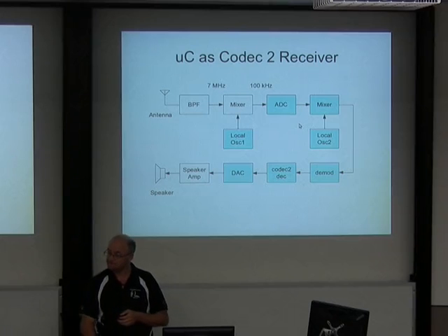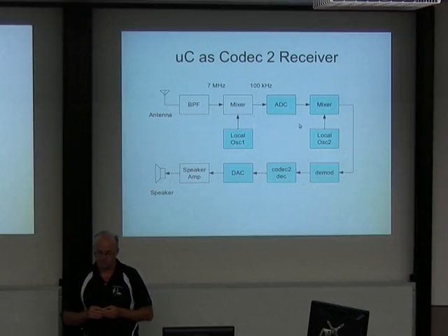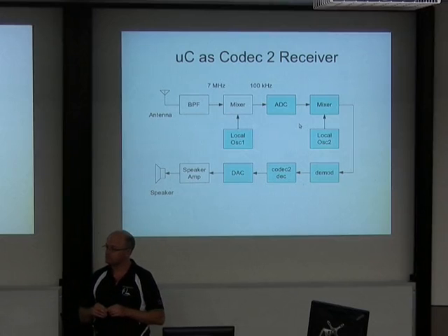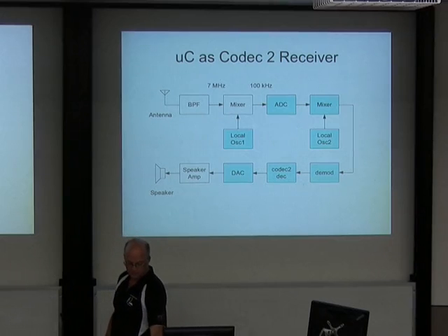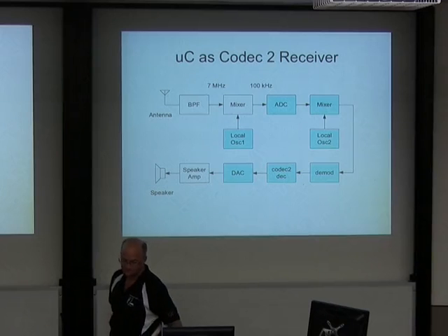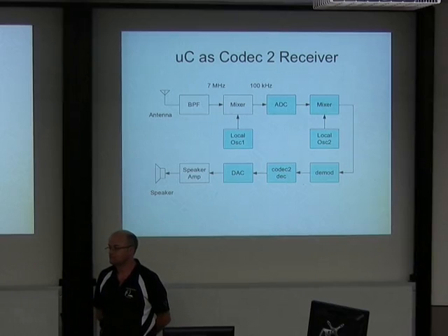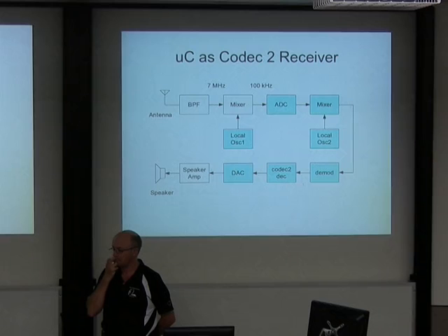So traditionally, what you've essentially got there is a superhet receiver. Yes. And traditionally, the point of a superhet receiver was to prevent noise getting in, so you mix it down to an intermediate frequency before you go down to baseband. I know there are a lot of SDRs on the market now that go direct to baseband before they go to the ADC. Why have you chosen to use an intermediate frequency rather than go straight to baseband?